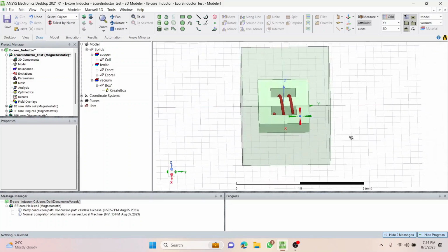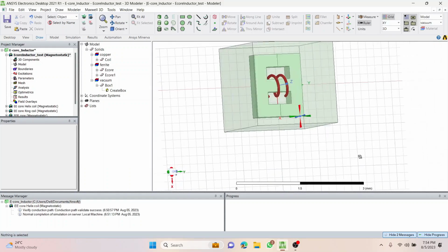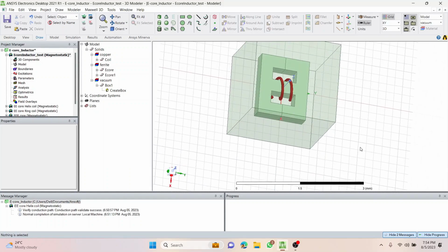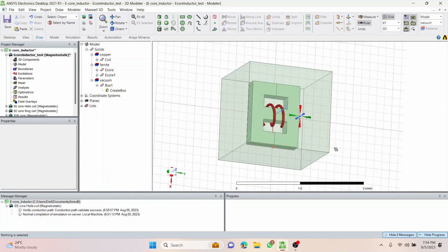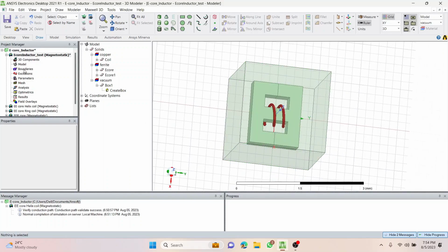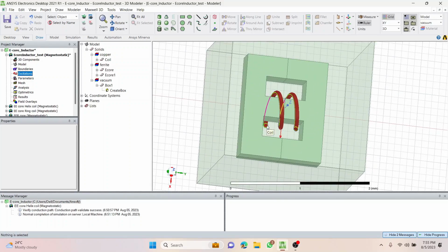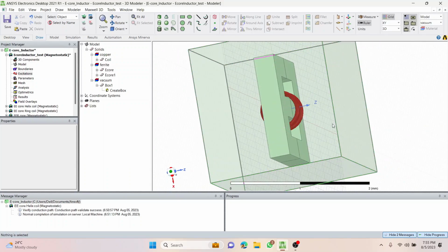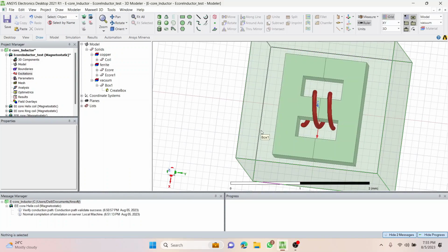Yet not so perfect. It is in the center, but one thing that we need to satisfy is the boundary condition, sadly. And the boundary condition, as we know till today, from what we have done, to satisfy this boundary condition, the extension for the excitation that we'll do in the next section, right? If I excite it right here, which is somewhere in the middle, and it is not touching the boundary, right? So boundary surfaces need to be touched to successfully complete the boundary condition. Now for that, we need to bring in the extensions. So let's draw the extensions first.